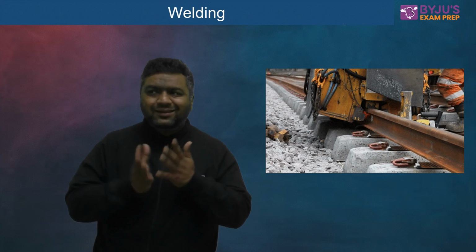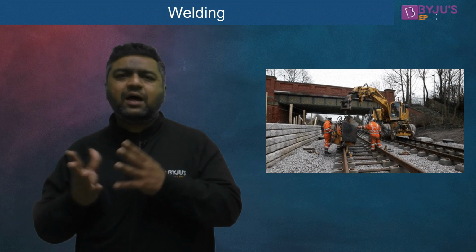for the same. The reason behind that is that a high value of current is required, so a very big setup is required for resistance welding. That is why we are not preferring this, because in India the railway network is very big. There are some places where maybe electricity is not there, but the railway network is there. So we are using thermit welding for the same. But yes, flash butt weld can be used.